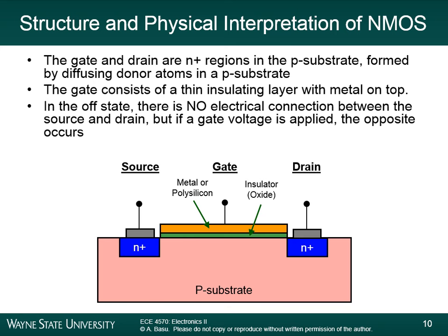Thank you. So the structure of a MOSFET looks like this. You have a p-type substrate. This is an NMOS device. I'm going to go over the NMOS device in class, but I think I can expect you to look over the structure of a PMOS device and understand the PMOS device by analogy. The same principles apply to the PMOS device. This is what the structure looks like. The source and drain are N+ regions. The substrate is p-type. We talked about this in class last time.